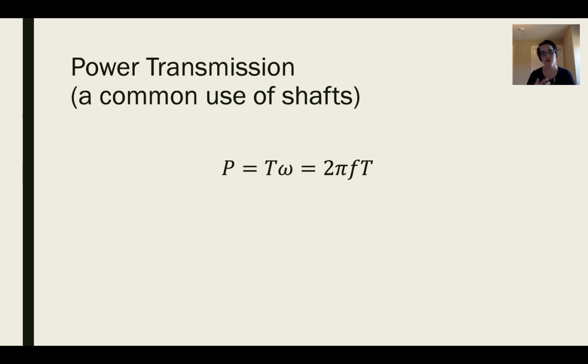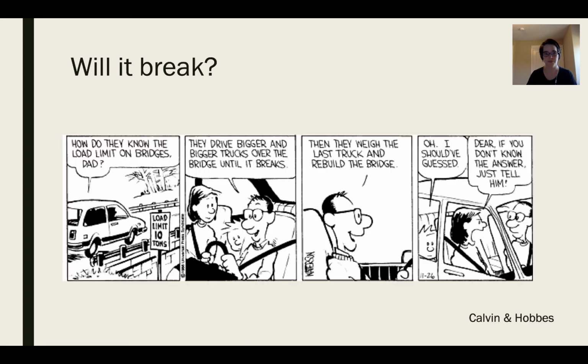So one of the things you'll see in some of the problems that we do is that they say you have a 5 horsepower motor, it's operating at 180 revolutions per minute, and then go in and ask you for a shear stress. So you're looking to think about what's the torque. When you hear those specifications for a motor, you're asking to think about what's the torque. And note that this frequency right here is in radians per second. So if you got motor specifications like I just said in revolutions per minute, you're going to need to do the math to get yourself to radians per second.